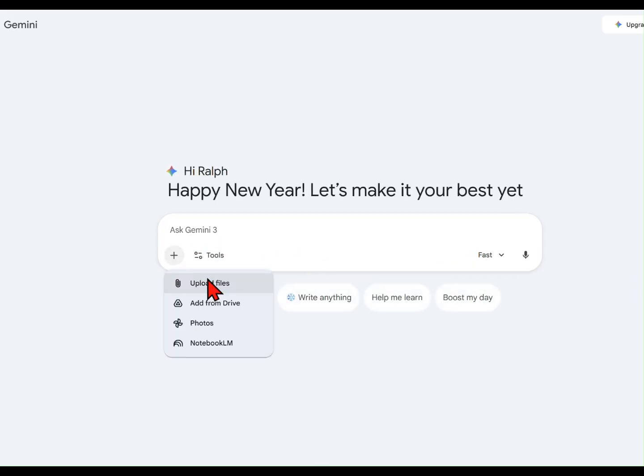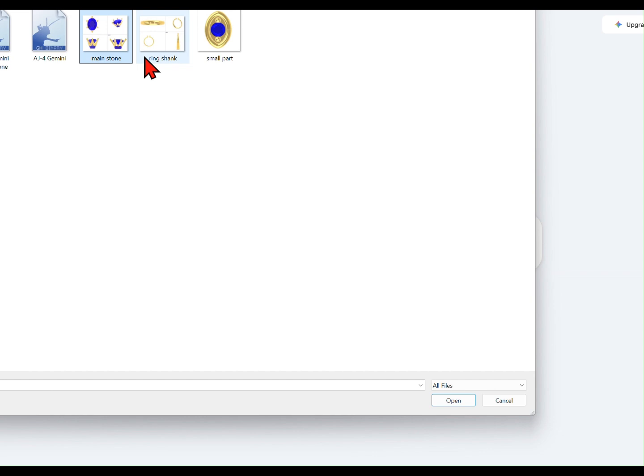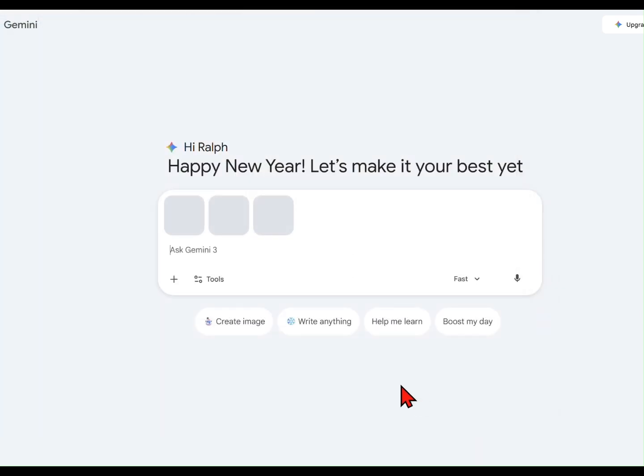Right, and for almost any ring design, the most important starting point has to be the Ring Sizer 1.1 component. That is the anchor component. It's the critical first step in every single definition because it instantly generates all the guides you need. The base diameter, the cylinder, the offset thickness guides. It handles international sizing, China, USA, Euro, and everything you build after that refers back to the radius it defines.